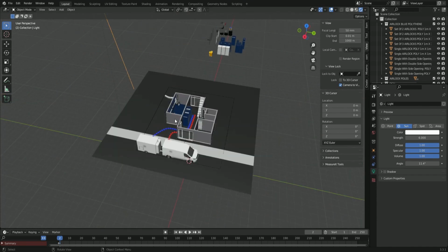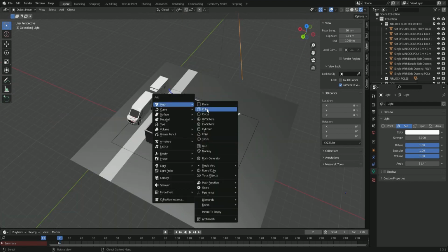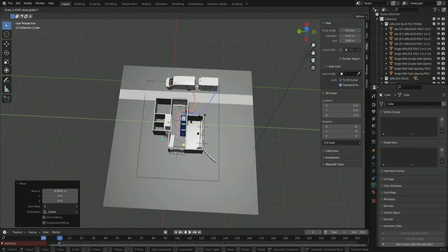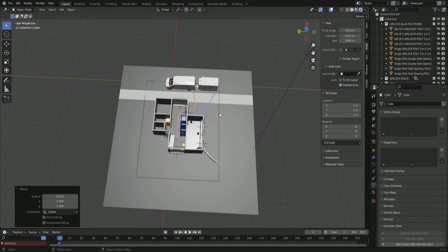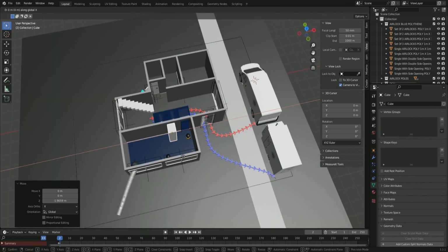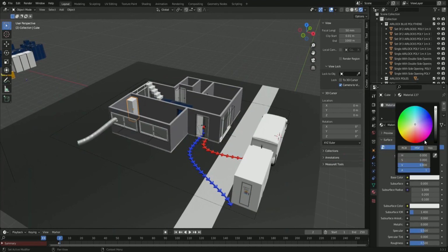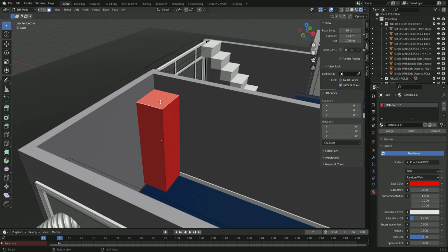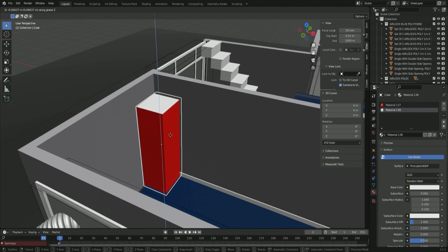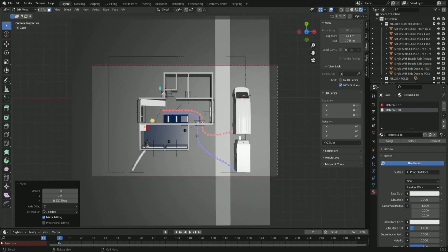There you go, a full asbestos enclosure drawing. Doesn't look bad, does it? Now you can just grab a cube, Shift A, remember, change the colour of it, turn it red. You can use this to represent the asbestos in the area as well if you want. Then just get your photos, and then in this camera here you can hide the polythene, go up to the top, render image, and then you've got your professional asbestos enclosure photos for your RAMs.